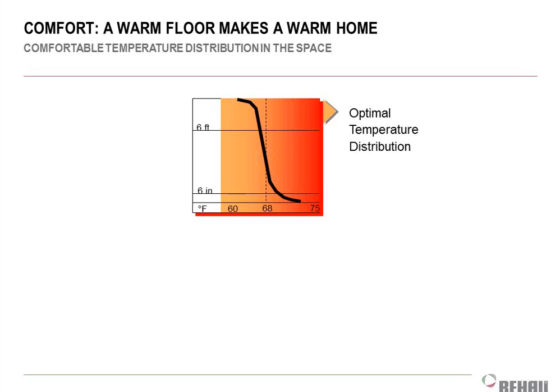And one of the things that standard also dictates is that from the floor, or they give you a little buffer, so from a few inches above the floor to the top of your head, you want the occupants to perceive no more than a 5-degree difference in temperature. If it's more than 5 degrees, people will perceive that as their feet being cold or their heads being hot, or both, right? And that's going to be an objectionable thing. And as you guys know, for that standard, you've got to get 80% of the people to be happy in order to really comply with the standard. We realize 20% of the people are crazy and you can't help them, right?